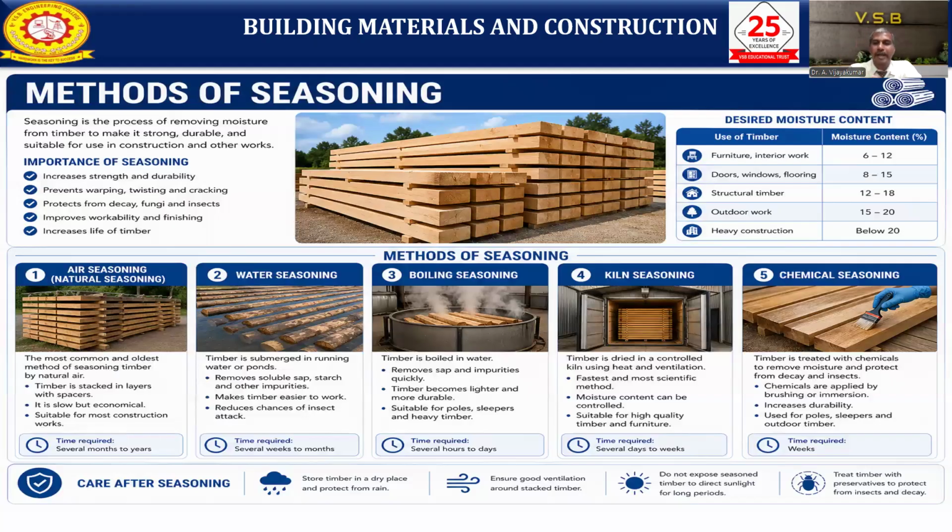The timber is stacked in layers, one by one, in a layer formation with spaces. Why give the spaces? So that air can move from one direction to the other. But it is very slow. When you stack a number of timbers, the seasoning is very slow, but it is very economical compared to other seasoning methods, and suitable for most construction work.